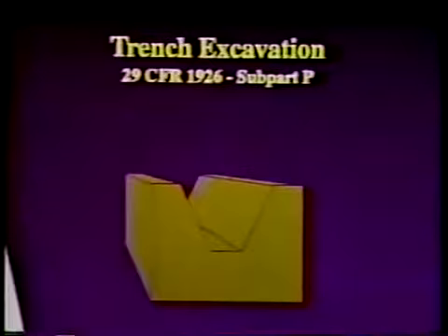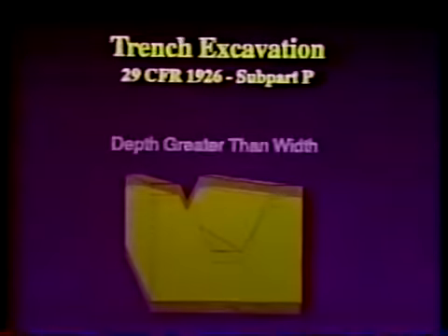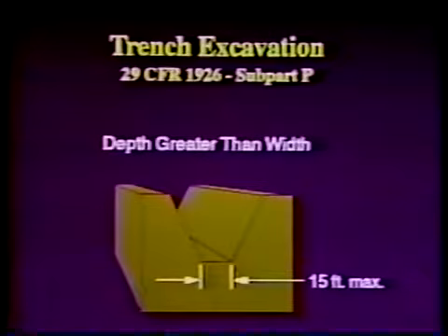OSHA's excavation standard defines excavations to include trenches. The standard states that, in general, the depth of the trench is greater than the width, but the width of the trench, measured at the bottom, is not greater than 15 feet. OSHA Standard 29 CFR 1926.651 contains requirements for the protection of employees against several different types of hazards of excavation-related work. Let's look at some of these.